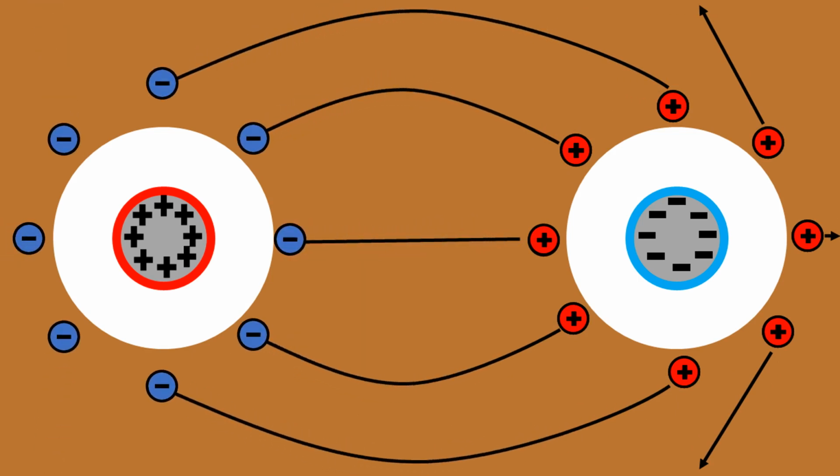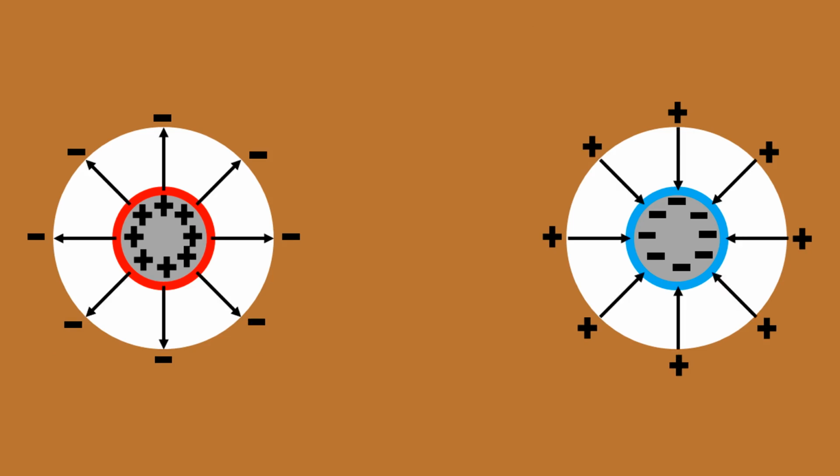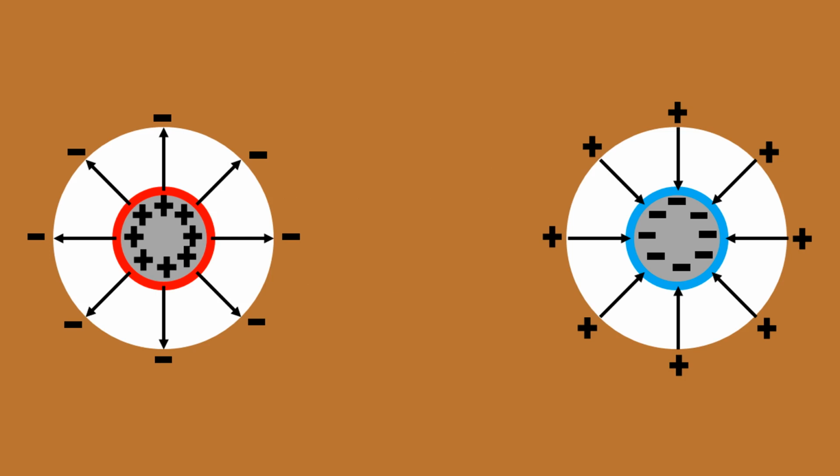The movement of these electrons creates a charge distribution along the walls of the two holes, and this distribution blocks the electric field lines from the wires, meaning that the electric field strength in the bulk of the copper becomes zero. However, the presence of charged particles so close to the wires also results in a much stronger electric field in the gap between the wires and the box. So while the Poynting vectors are confined to only the region between the wires and the box, the stronger electric field leads to a much more intense Poynting vector that compensates for the smaller area, meaning the same amount of energy is transferred by the Poynting vector.